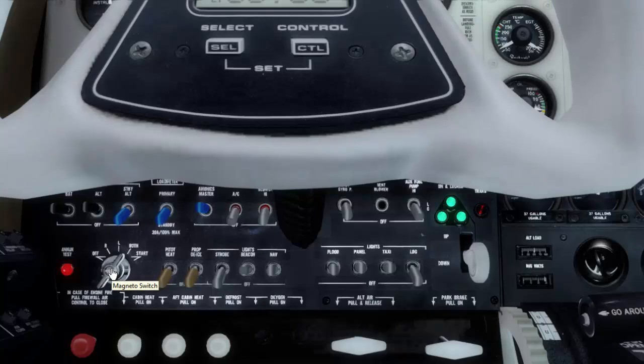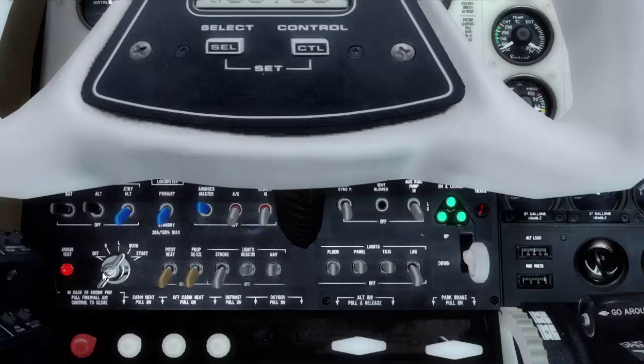And right now I will shut down the engine, so I will move the magneto switch to the off position, and also I will cut all the electricity inside the aircraft, okay. So you will see how the engine shuts down, okay. So right now I will put the magneto, as I told you, in the off position, okay, and listen how the engine is dying, okay.